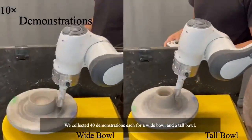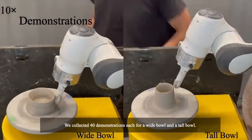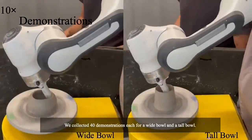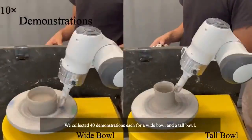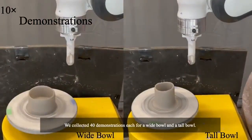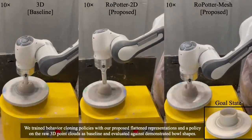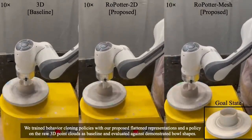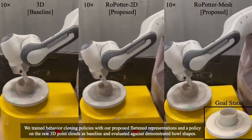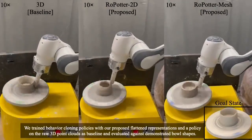We collected 40 demonstrations each for a wide bowl and a tall bowl. We trained two behavior cloning policies with our proposed flattened representations and a policy on the raw 3D point clouds as baseline, and evaluated against demonstrated bowl shapes.